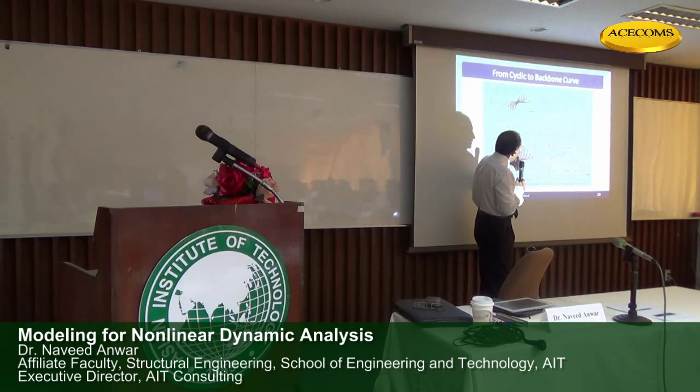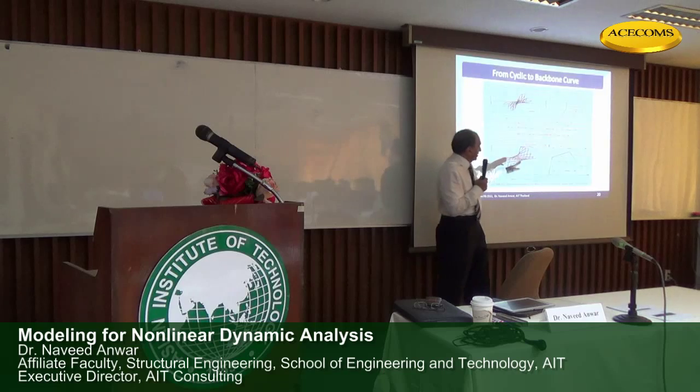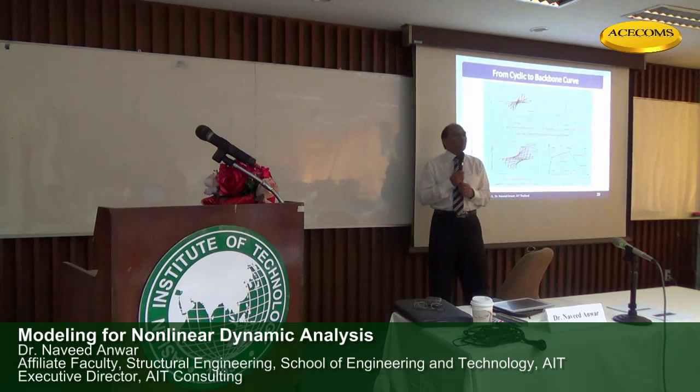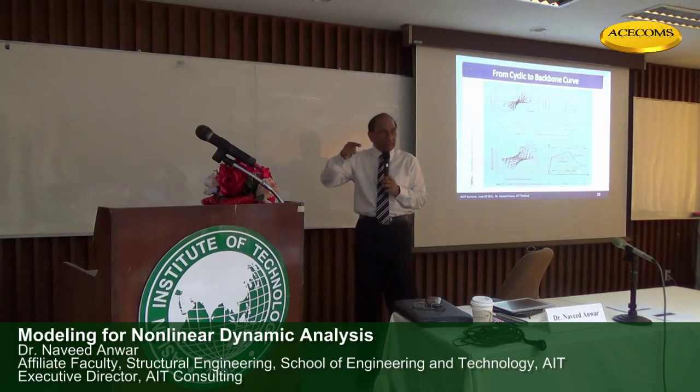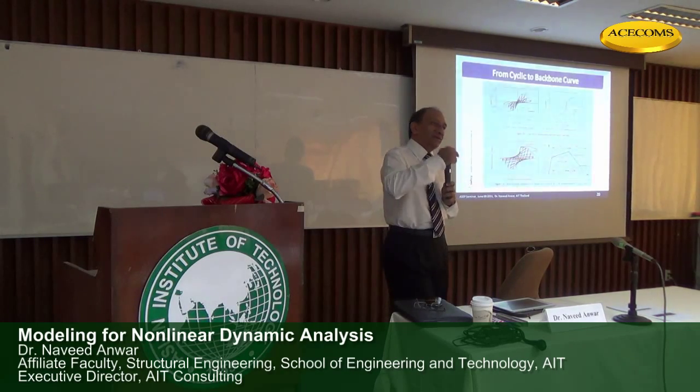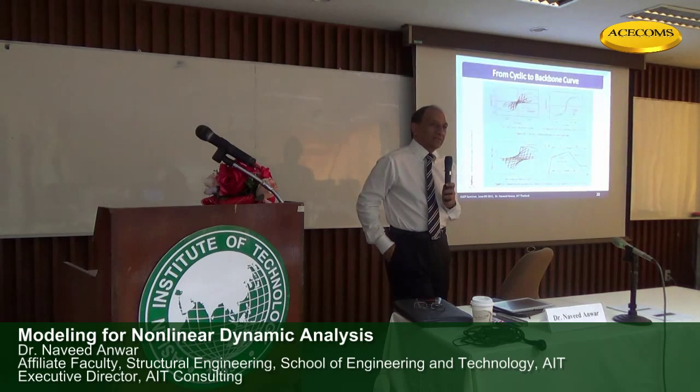curve. So this is the one that you will obtain if you test it only in one direction, and this is what you will get when you do the testing with cyclic included. So that means this degradation is actually coming from cyclic, monotonic going this way. And if we are able to include this modified backbone curve, that means we have indirectly included our cyclic response into the analysis. And that is what happens in pushover analysis.